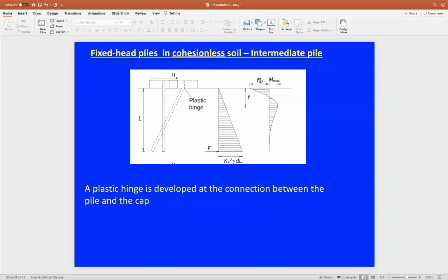And as we can see, we have here the My, we have the M maximum value, and we have here the distributions of forces on the systems. We have here until the point of the maximum moment points, and anything after that will cancel each other. That's for the calculation of the horizontal forces on the system. So the horizontal force in the system here will be equivalent to the distributed forces above the maximum moment points, or within the length F on the systems.